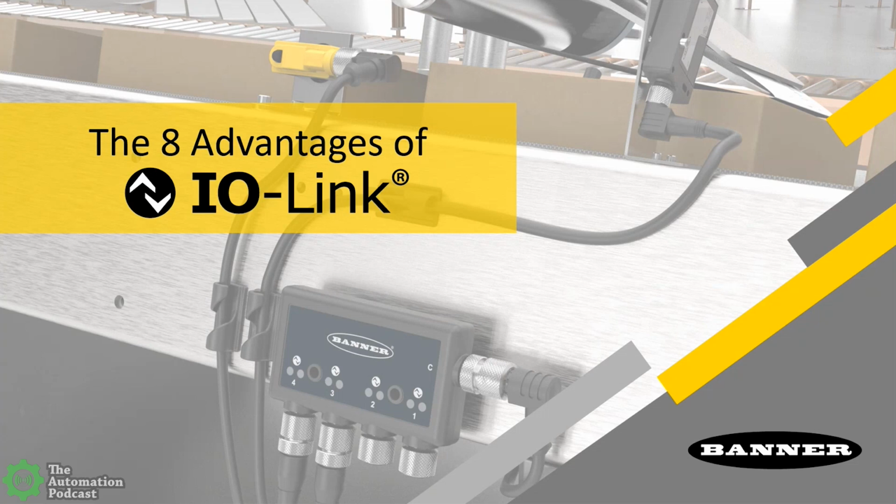Before diving into the advantages of IO-Link, Sean, I want to quickly talk about what exactly IO-Link is. In a nutshell, IO-Link is a standard point-to-point communication between an IO-Link master and an IO-Link device. It's important to note that IO-Link is not a field bus. An IO-Link system is quite simple. It consists of an IO-Link master and one or more IO-Link devices. IO-Link also runs on a standard 24 volts DC, which means, and this is huge, you only need to use 3-conductor standard unshielded M12 cables.